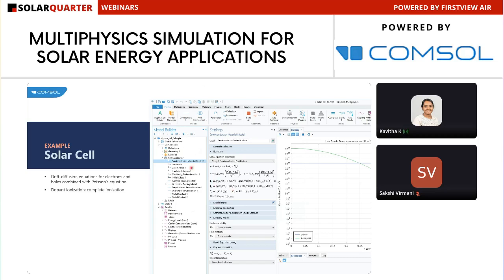So here the semiconductor physics interface shown here basically solves for the drift diffusion equation along with the Poisson's equation. In COMSOL, the beauty is that for any physics interface that you use, you can visualize the equations that you are solving for. And also if you are setting up different boundary conditions, you can see the equations that you apply at those boundary conditions, everything can be visualized.